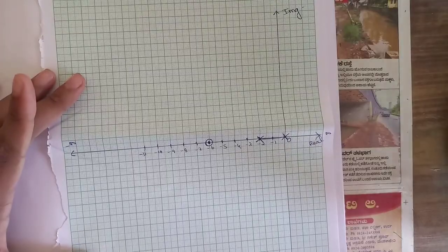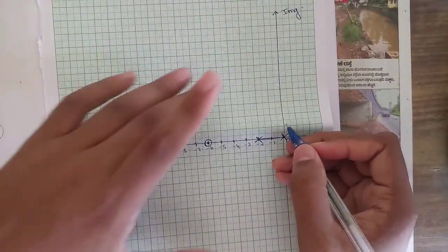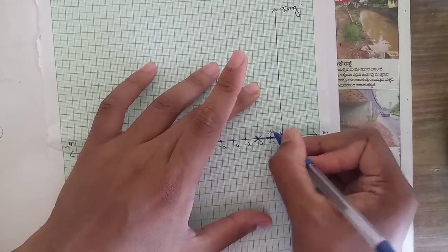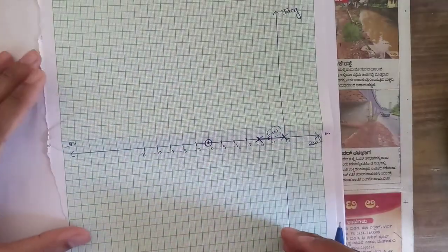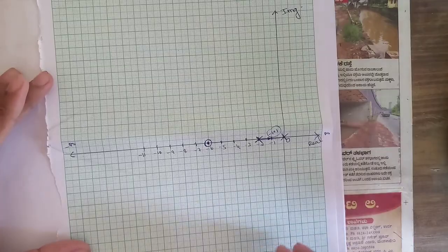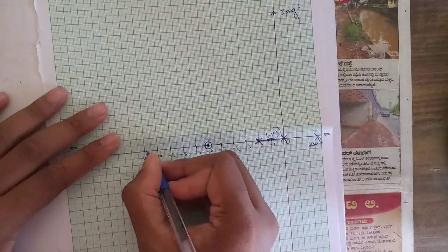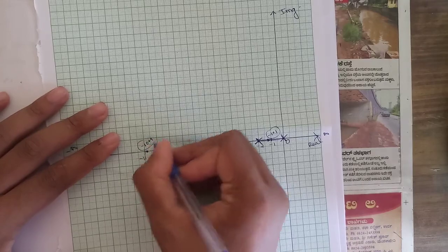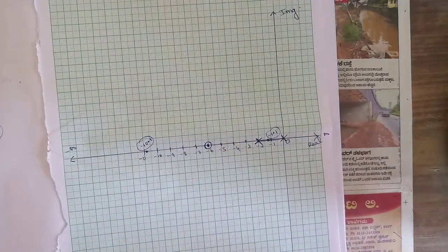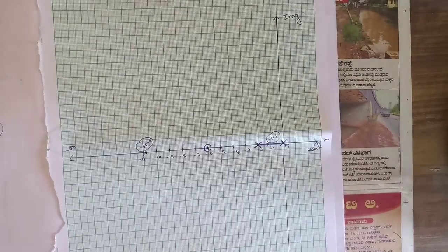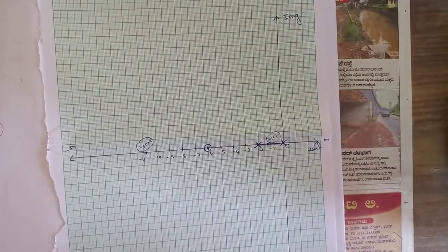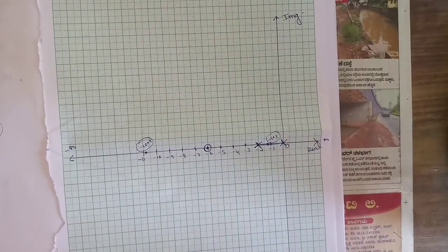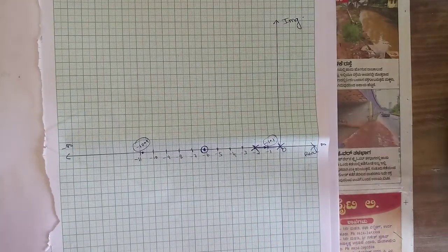So that's why we are getting two breakaway points. One breakaway point is at minus 1.1, so it might be coming here somewhere, and the other breakaway point is at minus 10.9, right? So this is that breakaway point, minus 10.9. So these are the two breakaway points here. I've highlighted it. Also in this case there is no centroid, so no angle of asymptote, so that's why it's not required. So now let's try to draw the root locus.